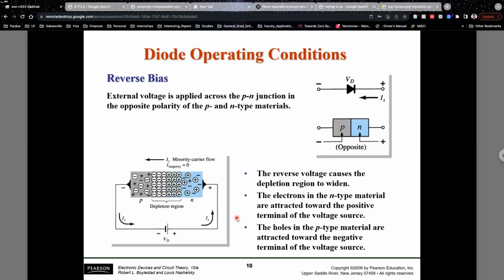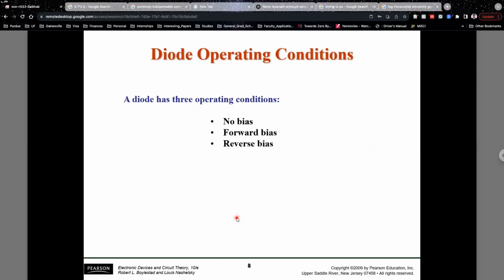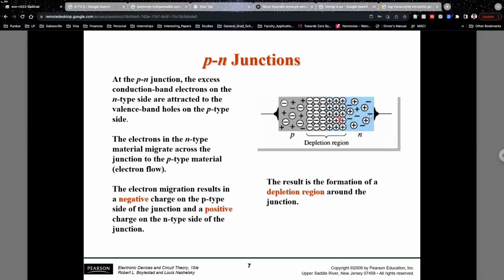If you go back to the original scenario when we talked about the PN junction, when you apply reverse bias, you connect the negative terminal of the battery to P and the positive terminal of the battery to N. Remember that we talked about minority carriers and not majority carriers. These minority carriers will create some amount of leakage current through the entire structure.